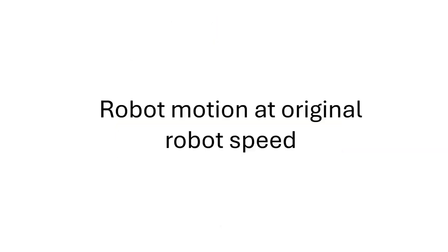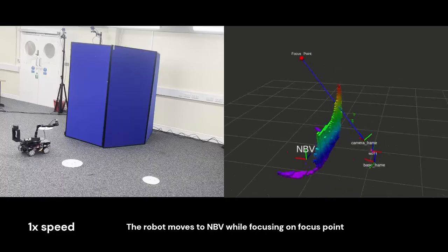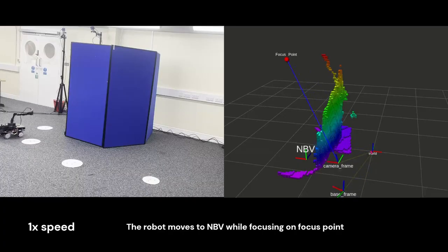We first present the reconstruction videos of the three methods individually until the first next best view to illustrate the robot motions at their original speeds. The first NBV and focus point are determined. The robot moves toward the NBV while focusing on the focus point. It avoids the obstacle and circulates around it. Once the robot has moved far enough, a new focus point is calculated. The robot stops focusing on the focus point to prioritize reaching the NBV.